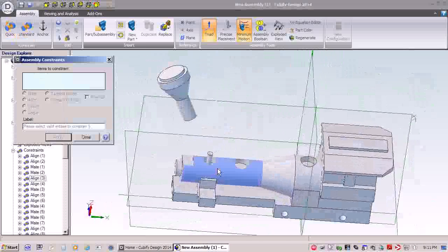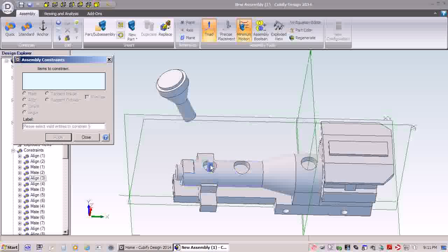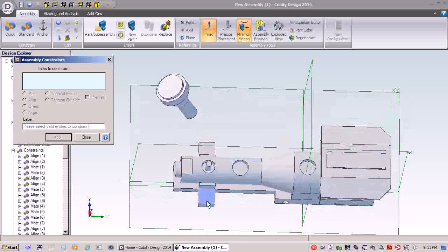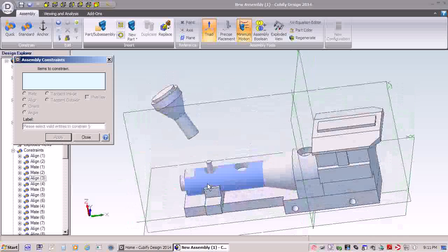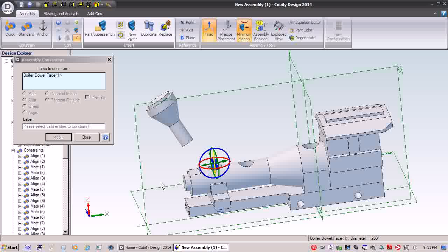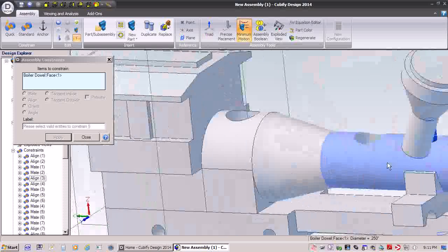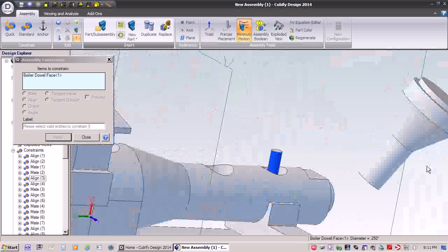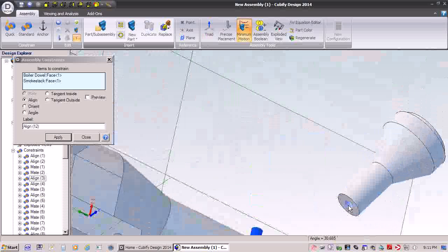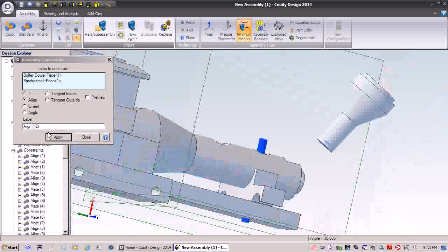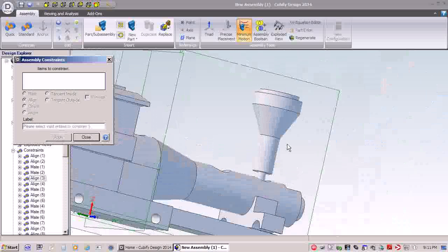And this dowel is a little tricky. This is a two-step process. I want to bring the dowel into the smokestack first, because if I don't, I'm going to hide this surface down here, and I'm going to want to use that as my second step. So actually, I guess this is going to be 3 steps because I want to do an alignment. And that's just a really awkward angle that that's at. There we go. So the line worked pretty well there.